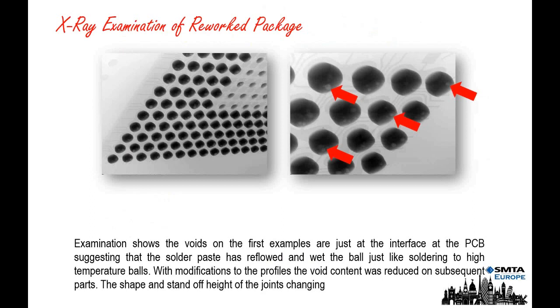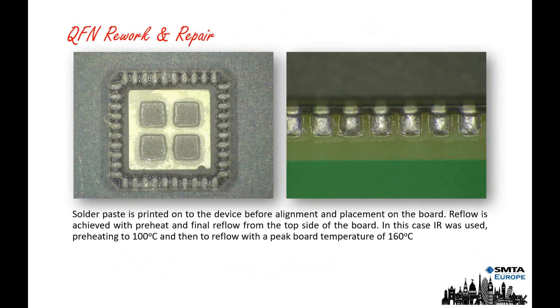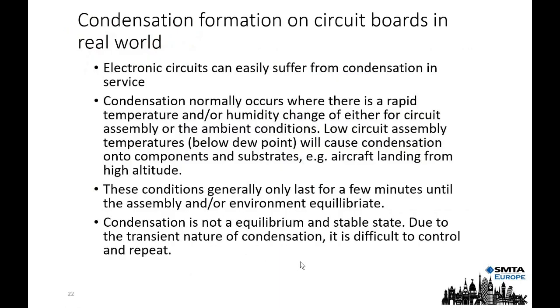We did shear testing, etc., and found those were potentially very reliable solder joints for a rework application. More recently, I've been doing some work with a good friend of mine, Richard Boyle at Henkel, and we've produced some test boards with QFNs, and they're currently doing temperature cycling. So we'll look at those results when we get together later in the year.